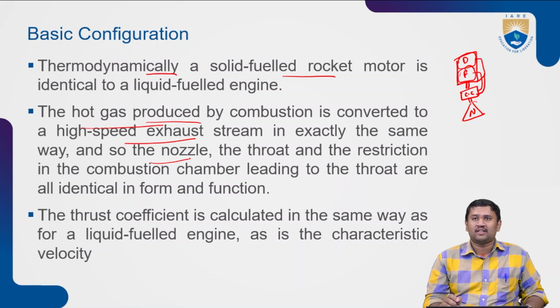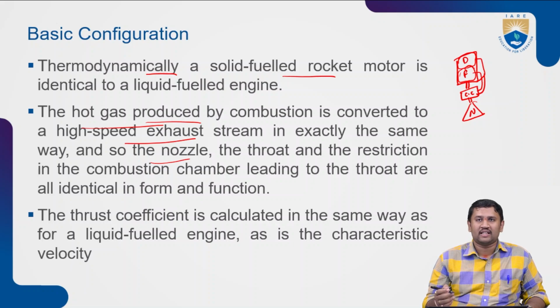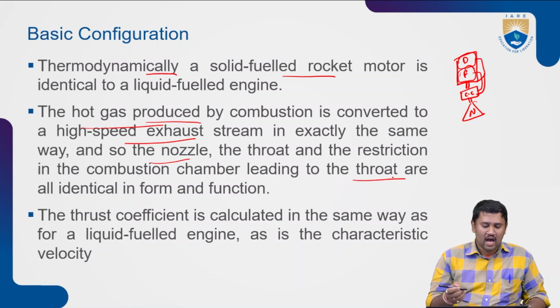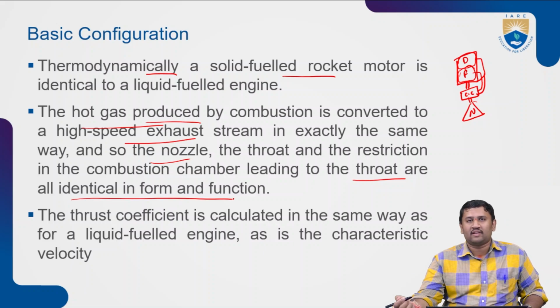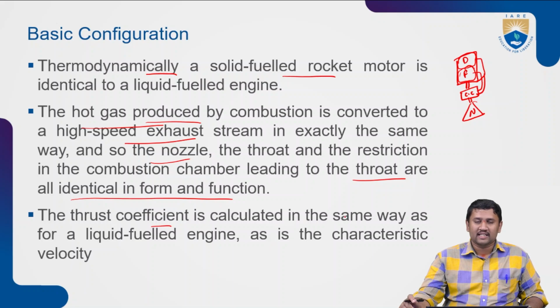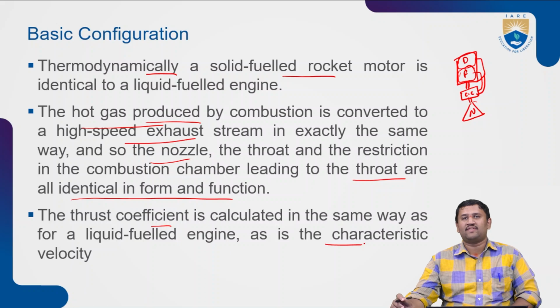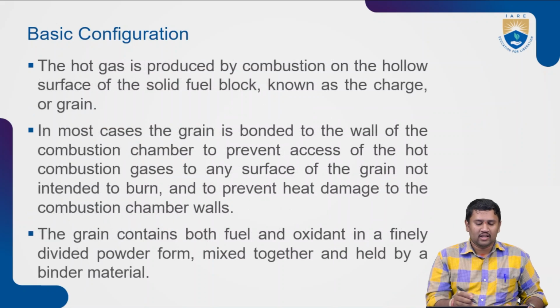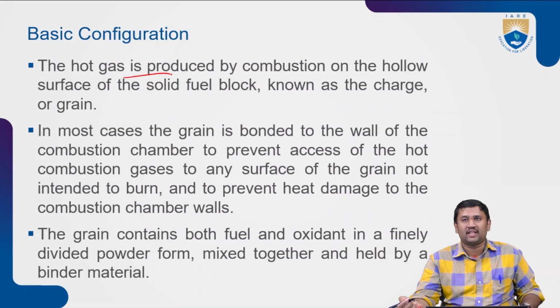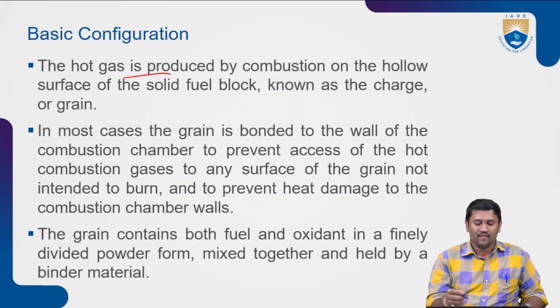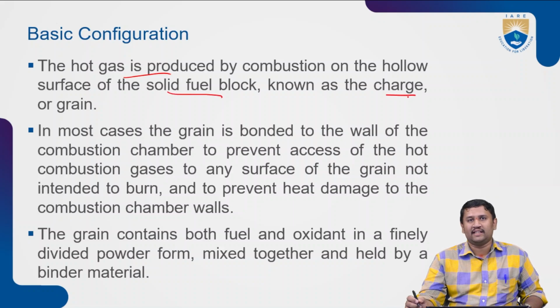So the nozzle and the throat, the restriction in the combustion chamber leading to the throat, are all identical in form as well as function. The thrust coefficient is calculated in the same way as for a liquid fuel engine, as is the characteristic velocity. The hot gases are produced by the combustion on the exposed surface of a solid fuel block, also known as a charge or a grain.